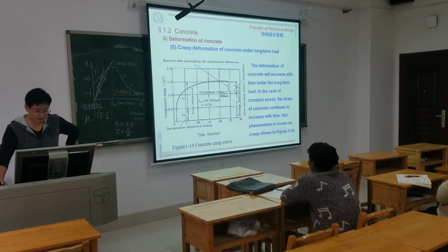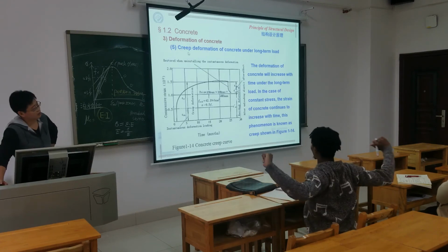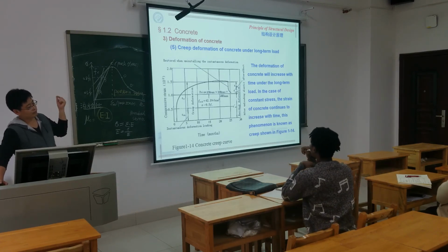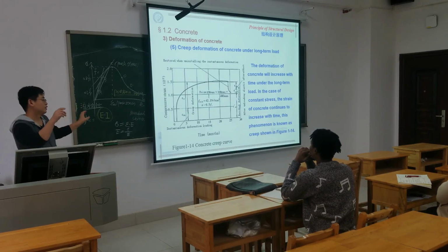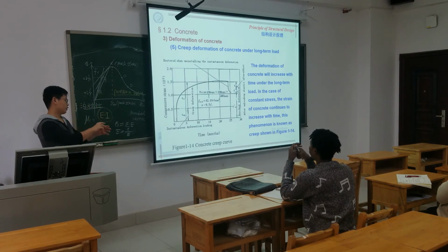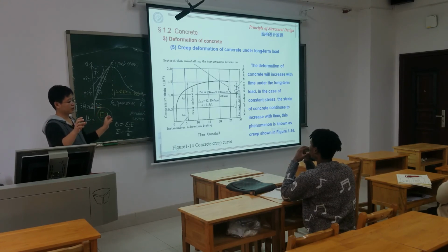Now, the creep deformation of concrete under long-term load. So what is the meaning of creep? Take a concrete beam or a bridge: you finish the construction, and even if you don't use it, there's no traffic, no person, no other force. That means the load is considered as not changing.